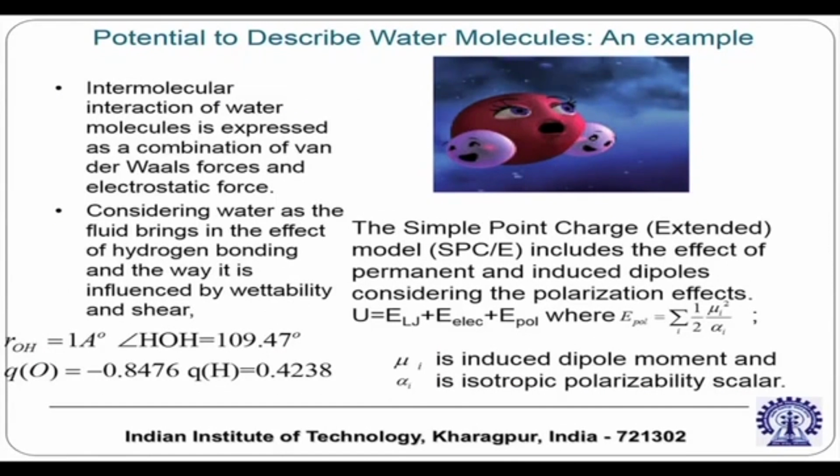Now in engineering we are many times interested in modeling water through nanochannels. So how do you represent the interactions in water in a molecular dynamics framework? Intermolecular interaction of water molecules is expressed as a combination of van der Waals force and electrostatic force, and the electrostatic force is very important because the water will have a dipolar behavior.